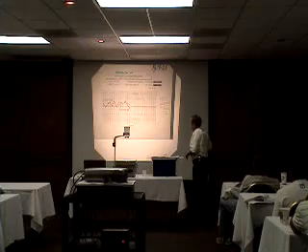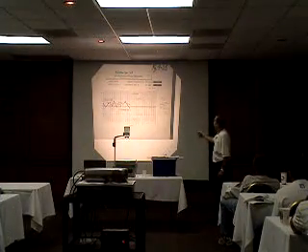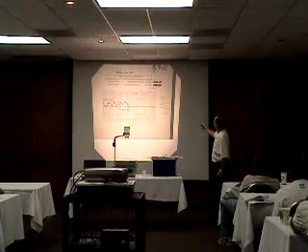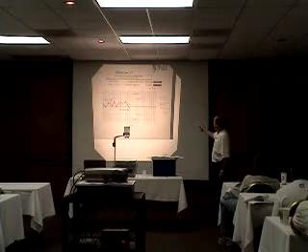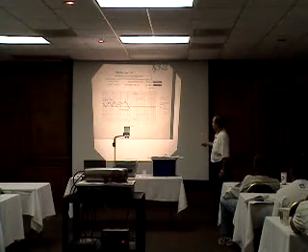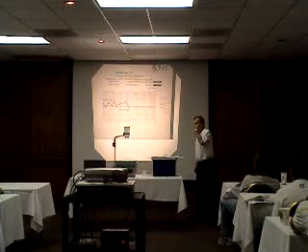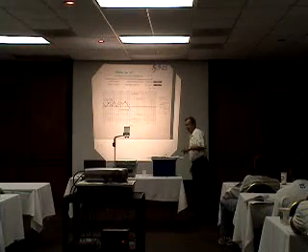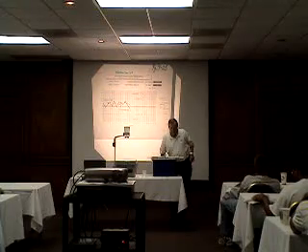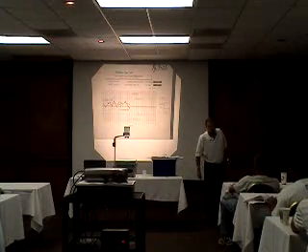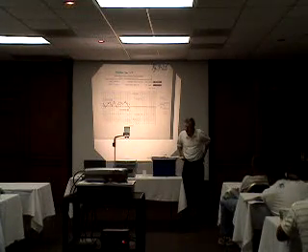The lines that we're looking at, well, first, back to the center line. Remember, this is our target line. Here, we're checking the .075 millimeter sieve, and the target was set on 4. That line represents 4. Then we plot what's known as the moving average limits, and then the individual test limits. If you look on page 722, you'll see a set of control limits there in the boxed off area.